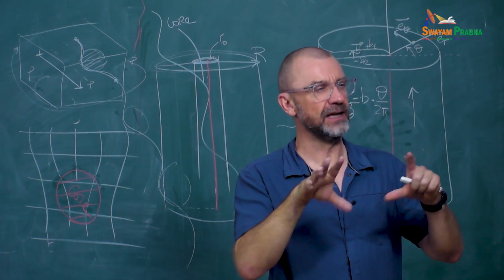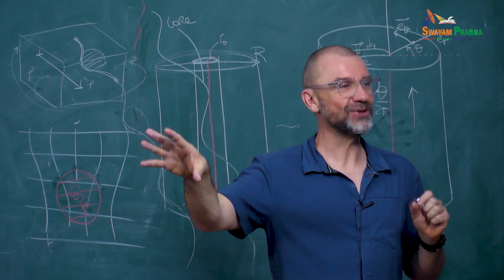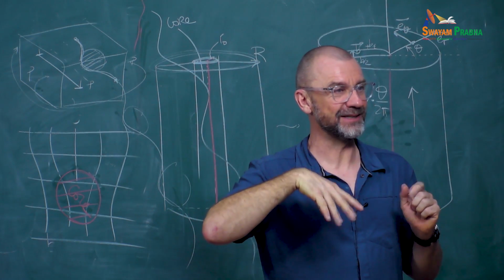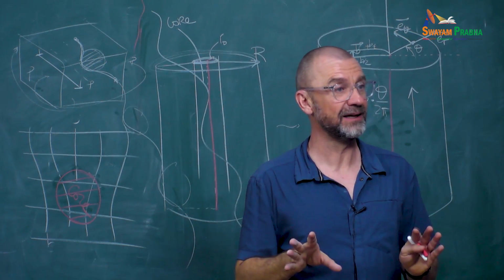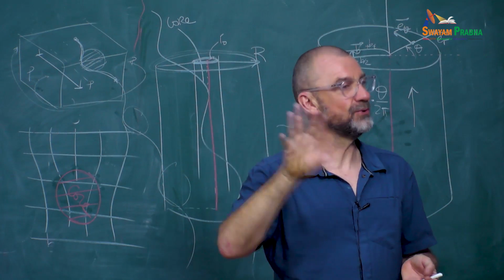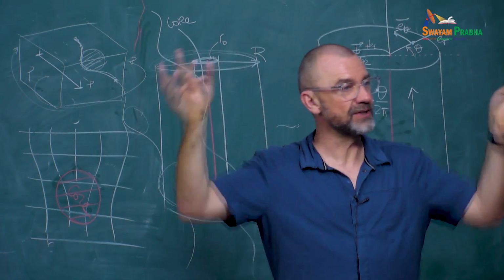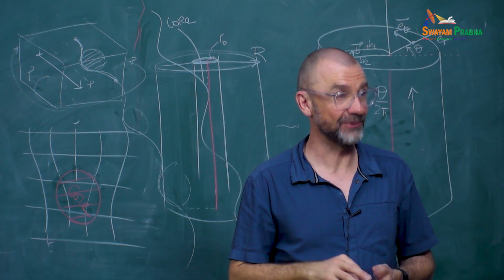We computed the core energy in part to show how to calibrate dislocation dynamics from atomistics. If you do the calibration correctly, your dislocation dynamics calculation will reproduce exactly the atomistic, and then you can put many dislocations and look at more complex interactions.